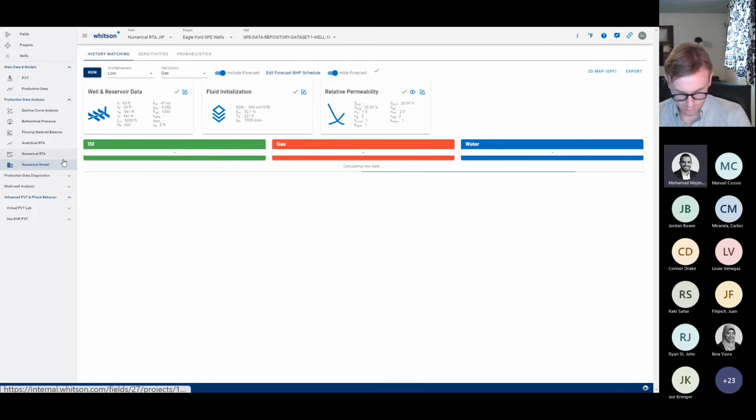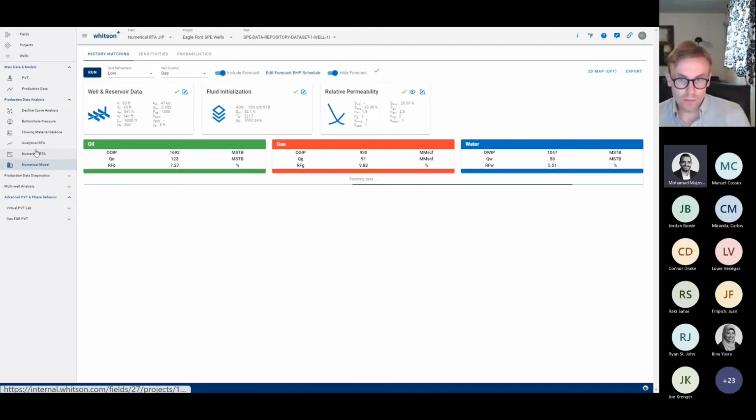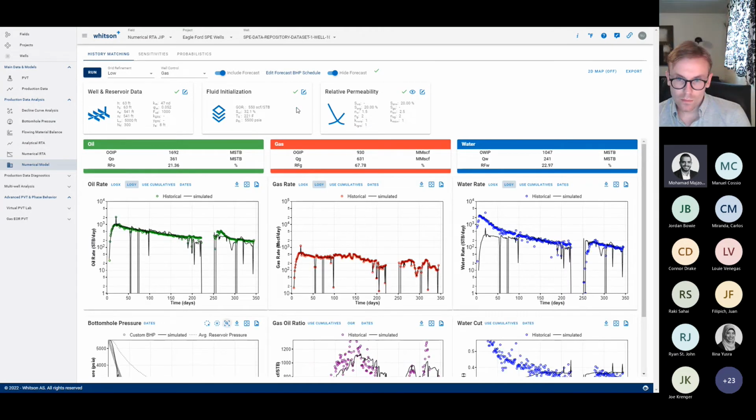The one thing that I see more than just having the data is sometimes it's also about which of the data you have that is fluctuating. So let's say you don't have bottom hole pressure data, you have oil and gas rates, but you see that there's definitely something fishy with your gas rates, then you just go and control it on oil rates, even though that's not the preferred choice in most cases. So trying to honor the data that you think is most reliable is what most people are doing.